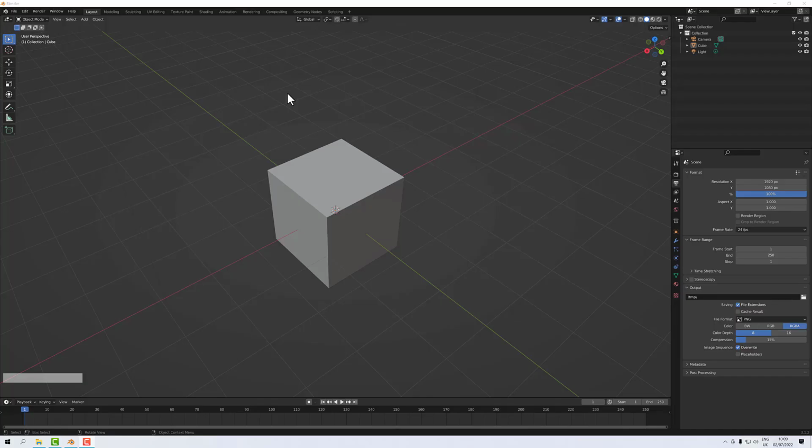Okay, so the next thing I'd like to look at is splitting the screens. You can split your screens in many ways, or in many subdivisions in Blender, and it took me a little while to get my head around it, so I thought I'd include it in this. So you can see my cursor at the moment is a normal cursor, but if I point up in the top corner there, top right, I get a little cross, and that's indicating it's the right spot to split.